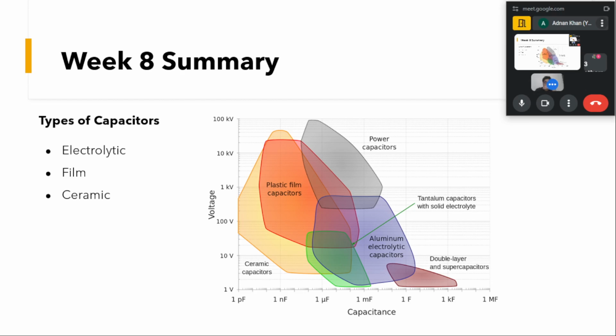Also, these electrolytic capacitors are polar capacitors. They have a proper positive terminal and a negative terminal, and you have to take care to connect the proper terminal to the proper bus. Otherwise, these capacitors would get damaged if we do not connect them properly.